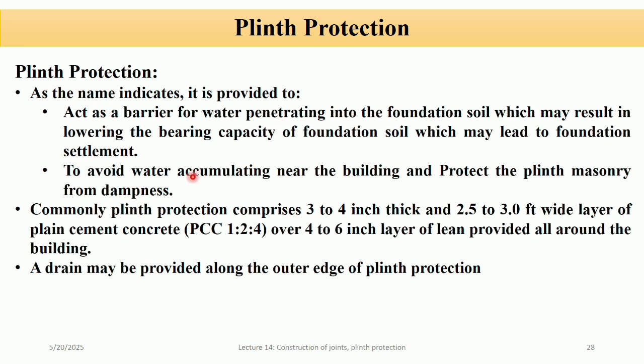And to avoid water accumulation near the building. By providing a hard sloped surface, plinth protection helps drain water away from the building, preventing waterlogging near the foundation.